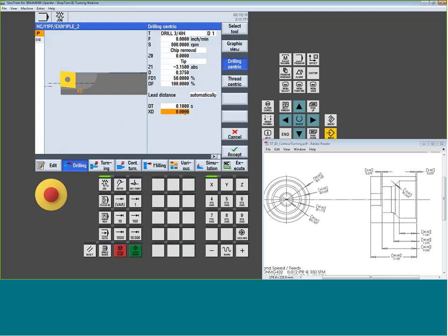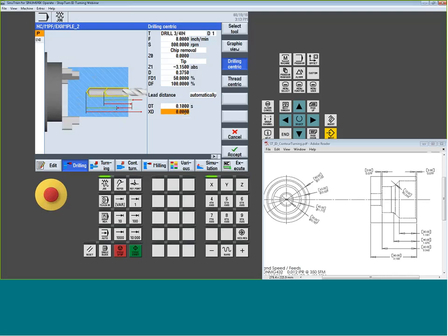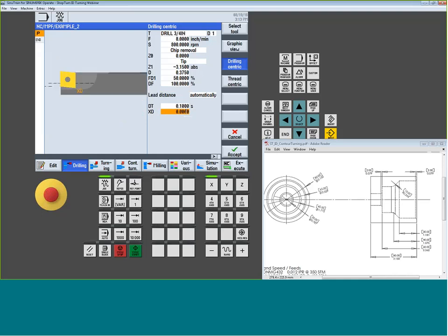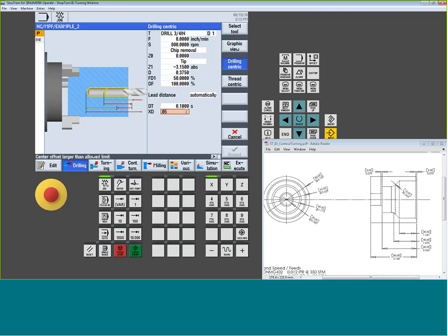Now, this is how we adjust for that offset for that insert drill. So remember earlier I mentioned that with an insert drill, you don't have to drill right at 0. You can actually make the hole oversized to what the tool is. So that's what this XD value is. Now, it's important that if you're going to do this, you go to your tooling catalog, whoever you bought the drill from, and they will give you a maximum offset value that that drill can handle, and you have to stay within that range. But here, then you would just literally put it. So, am I going to offset it 50 thou, or not half inch? That's big. 10 thou, whatever I'm doing, and it'll offset it.